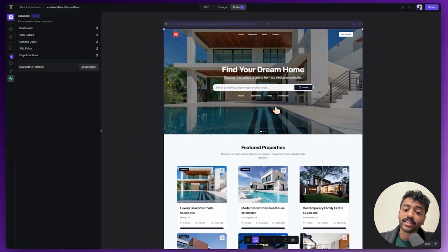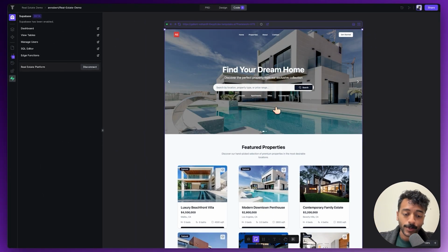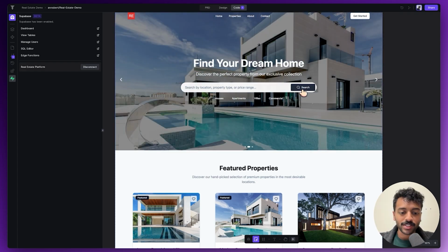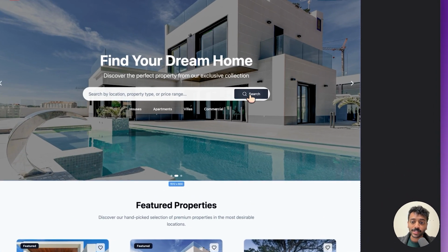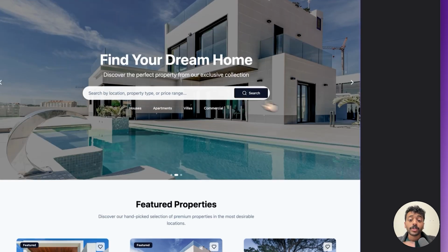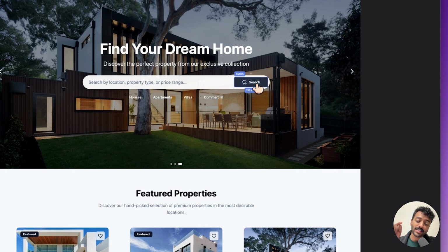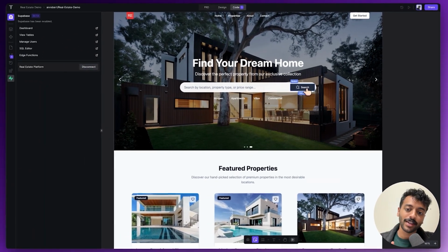Now, by default, the select tool allows you to click on elements top down. In code, there are often more DOM elements than design, so you might find yourself tempted to click many times to access a deeper element. A useful shortcut is to hold down Command while selecting, and you are able to access the deepest element in the tree and navigate bottoms up.